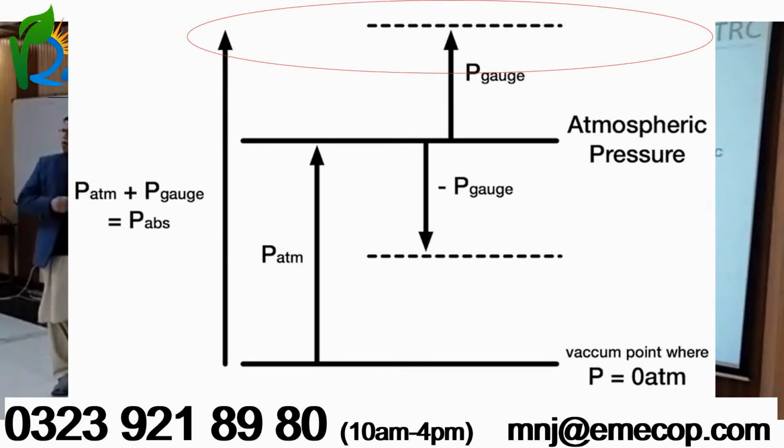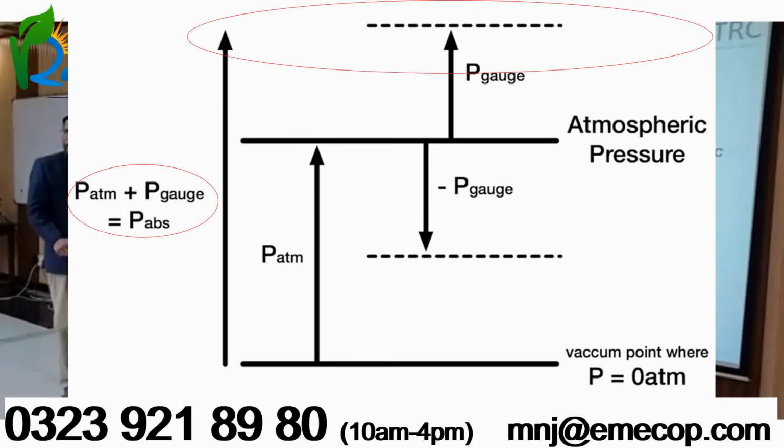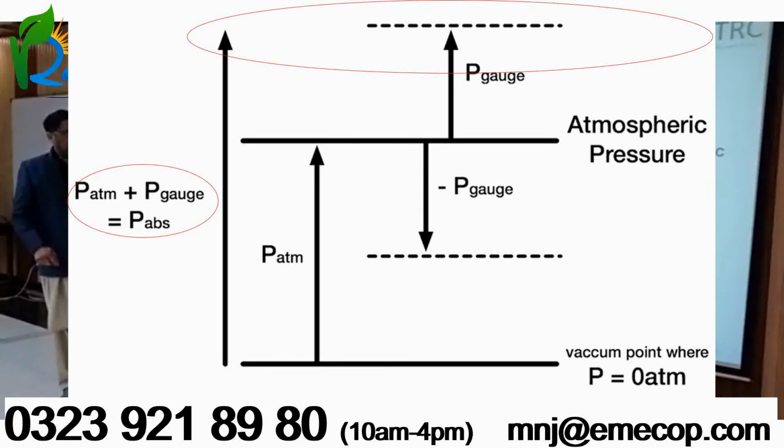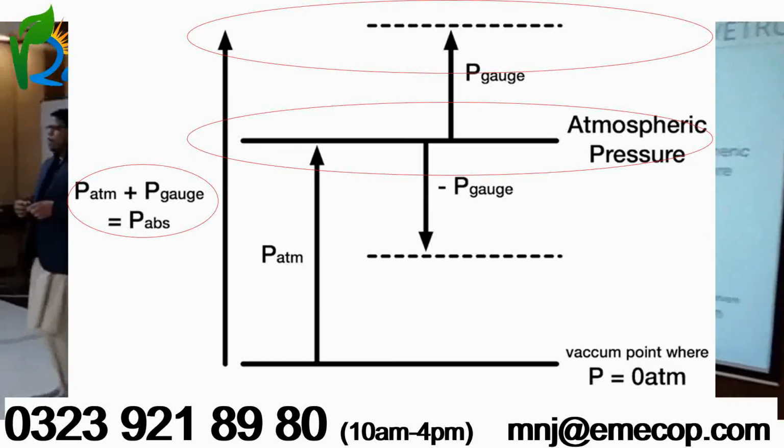And if I install a pump with a pipe and run the system, the pressure within the pipe will be the sum of atmospheric pressure along with the gauge pressure that arises due to the installation of the pump or any other arrangement. So the gauge pressure plus atmospheric pressure will become absolute pressure. And if you decrease the pressure in the piping network by any arrangement, basically you are creating a negative pressure, so we call it a vacuum. But 100% vacuum is not possible.